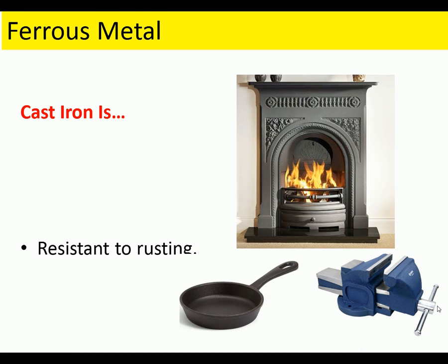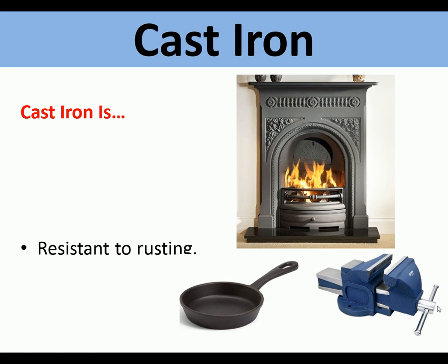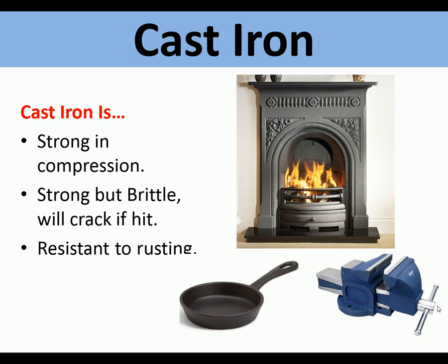This ferrous metal is cast iron. Cast iron is strong in compression. It is strong, but is brittle and will crack if hit or has impact, so it's very susceptible to impact. It is resistant to rusting and it can easily be cast into ornate shapes. So the fireplace here is cast iron.